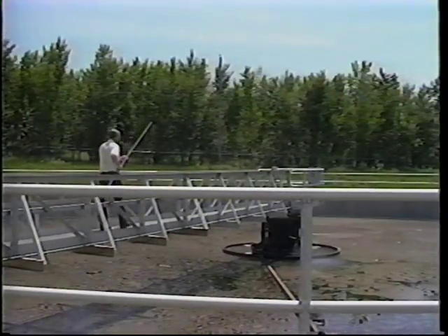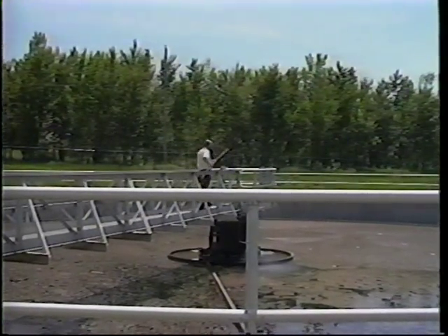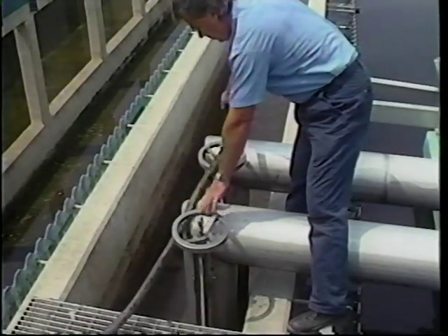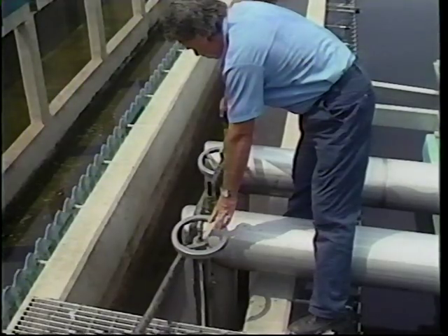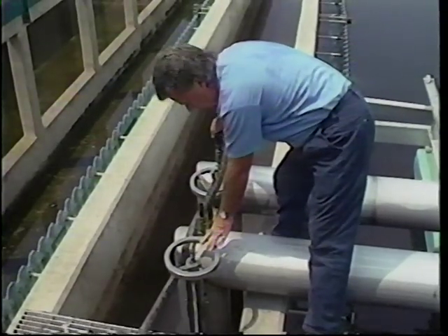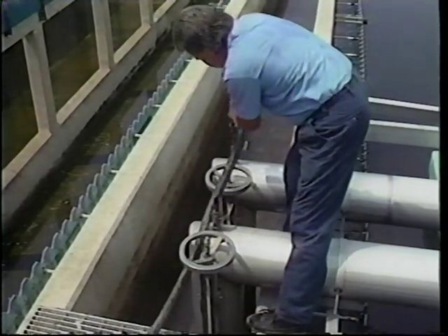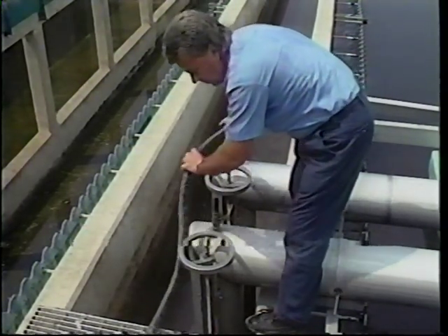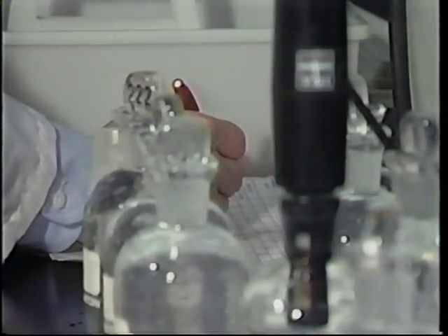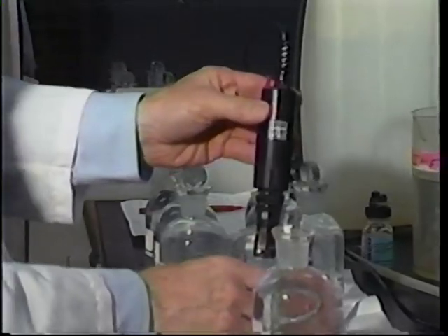In any event, the activated sludge is removed from the clarifier by means of the sludge collection mechanism that may utilize pumps, airlift, differential head, or a siphon mechanism to remove the activated sludge from the clarifier. It is essential for the operator to carefully control the amount of activated sludge returned and wasted from the clarifier. The amount of activated sludge returned or wasted is dependent on hydraulic and organic loading to the system. Only through proper process control testing and monitoring can the operator make the proper decisions and adjustments.